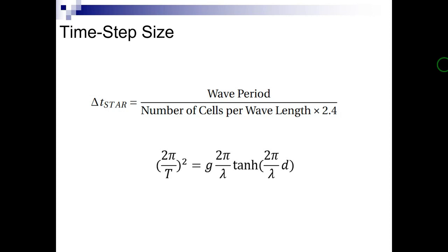By using these equations, the time step size is estimated as 0.013 second. However, note that the estimation of the time step size should also be such that in each time step the overset mesh moves a distance smaller than the size of the smallest cell in the background mesh.